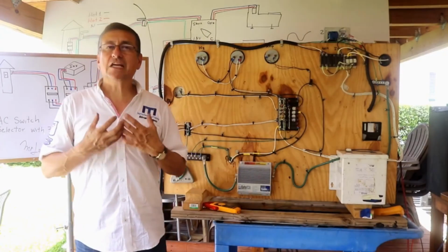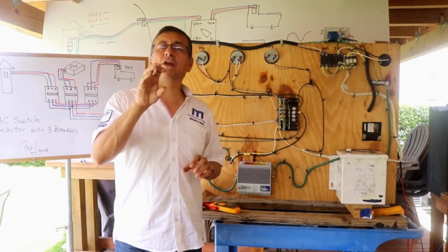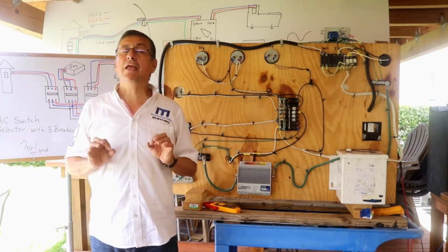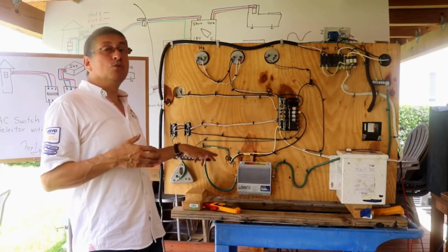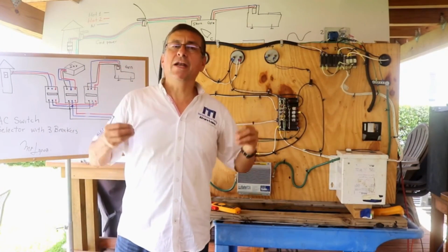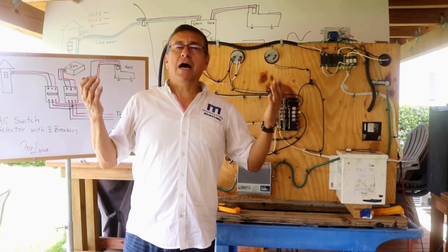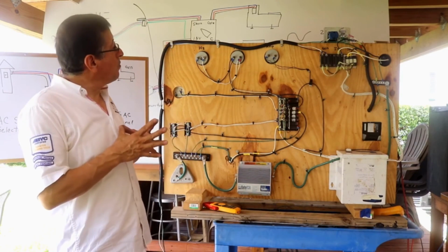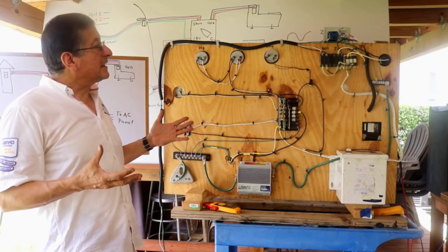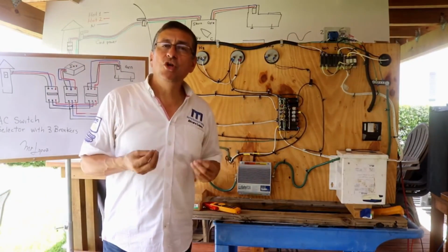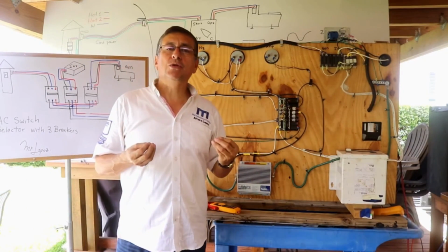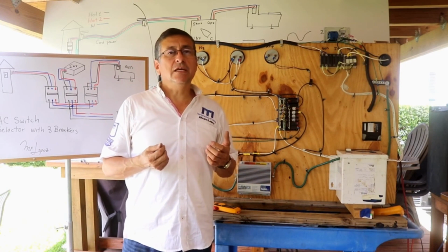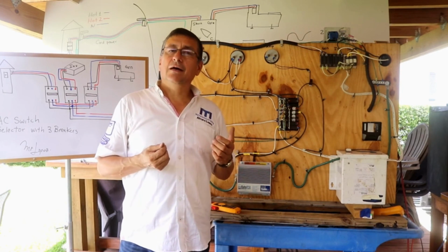This is catastrophic. For that reason, if the reverse polarity indicator light is on, you need to solve the problem immediately. If not, probably your bonding bus bar right now is powered with AC power, 120 or 240. Be careful with that. This is the procedure to do the wiring in AC power. I think that it is simple. You need to be careful, use the appropriate tools, and use goggles. Be careful with the AC current. The AC current is critical.